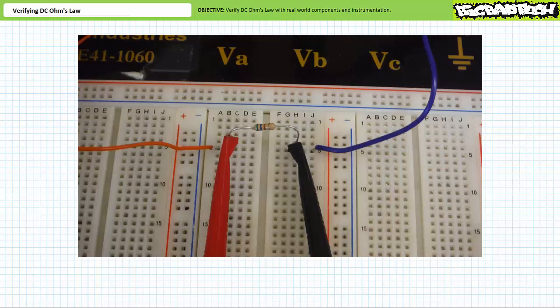Additionally, recall that the resistance of a parallel configuration of elements is always smaller than the smallest resistor constituting the parallel relationship, and that 0 ohm shorts inside parallel configurations effectively short out the entire parallel configuration. An ammeter configured in this fashion will present no opposition to the source, and theoretically infinite amounts of current can flow. This could damage the meter, your circuit, or yourself. Never, ever put an ammeter in parallel.